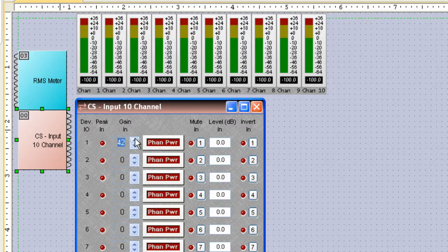For most microphones, that will mean 42 to 48 decibels of gain in the analog world. Some wireless microphones are at about 36. For most line level sources, if they're consumer, they're typically coming in at a quote -10, and the Nexia is looking for +4, which means we should set our gain at about 12. With some professional sources that are coming in at line level, we can go ahead and leave it at 0.